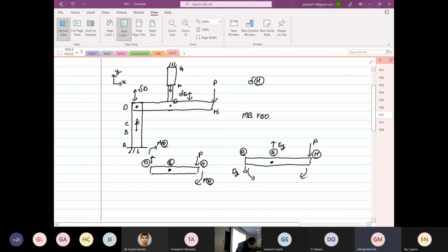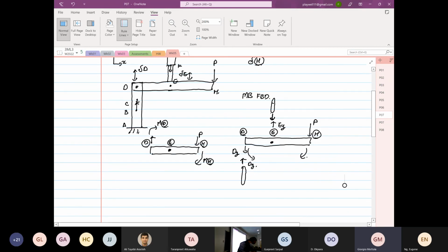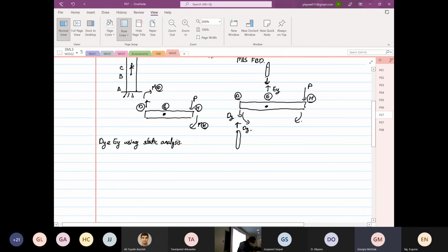Okay. Then you start drawing this, and I taught this in week number 1. So Ey is in this direction now. Tension. Dy is also in what? Tension. Okay. So the first thing is to find, from here, Dy and Ey using what? Static analysis. Then after that, you...